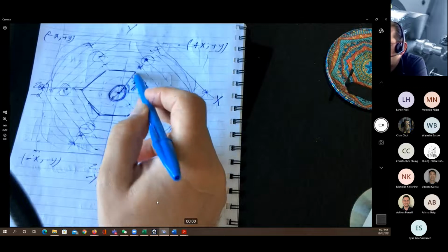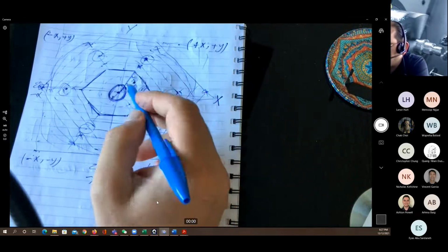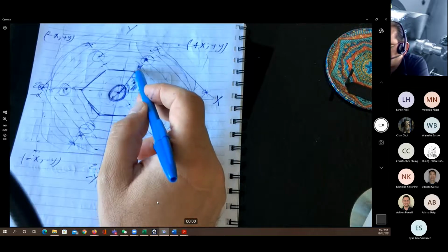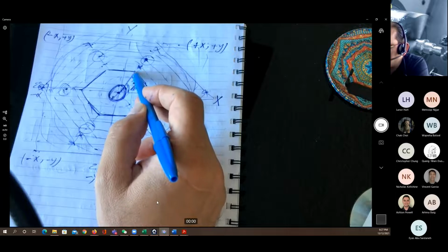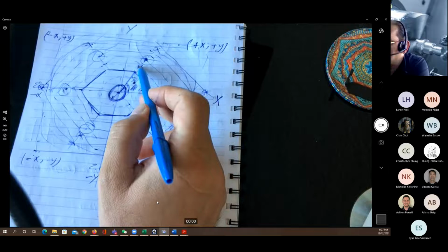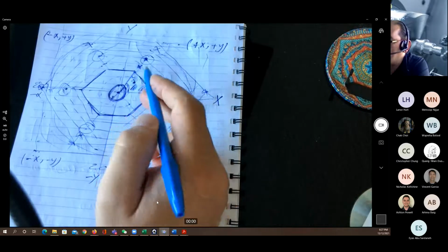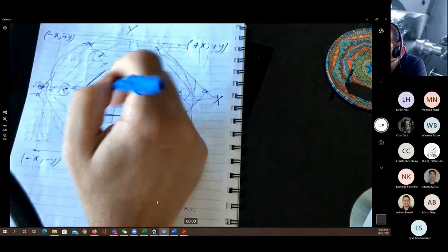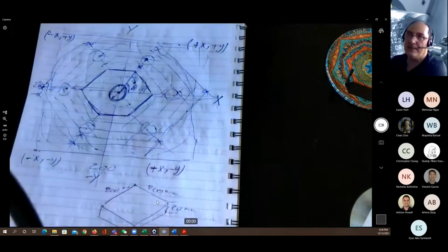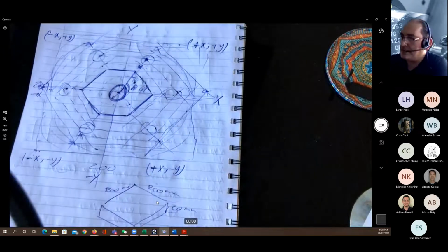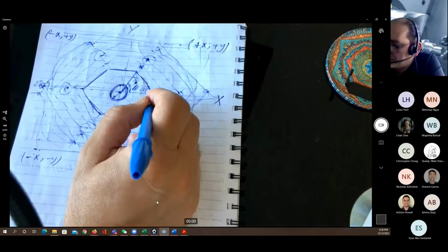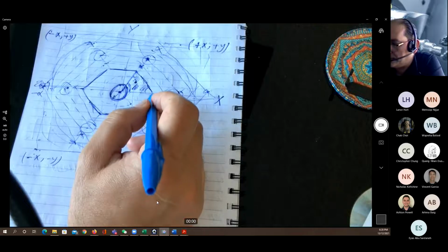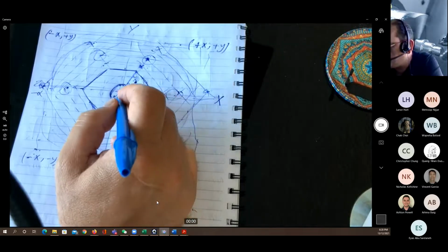We can calculate the chord of the triangle, and then I can find what will be this distance. So I can find this location. Just remember that this point is going to be offset by the radius of your cutting tool. So I can find this point as the X and the Y. Whatever I'm going to find here, I only change the sign and distribute around the work part. For this one, it's going to be very simple because it's going to have 0 for the Y and a value for the X, which is going to be equal to that length.